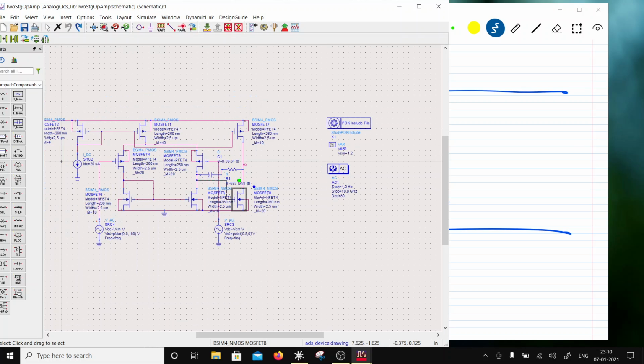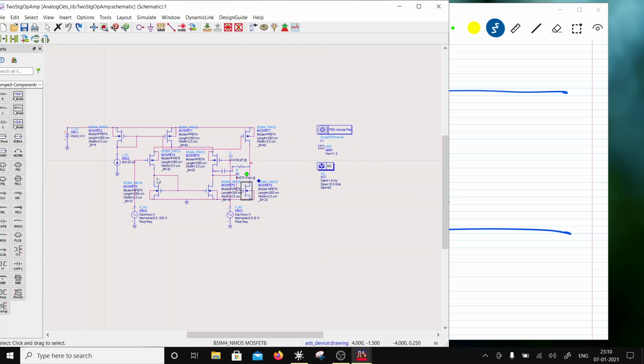So in that case it becomes a three-stage op-amp. In the next session I will discuss the source follower, its frequency response and stability, because that has a complex pole which can cause ringing. Then you have to load that with enough C, or RC, that it doesn't have a lot of overshoot, or the ringing is minimum. So we will look at the condition for a certain overshoot, right? Right now the op-amp has two stages and it can drive a capacitive load.